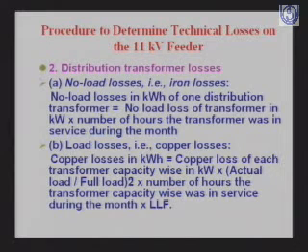So you can see that this ratio is in square. So if the transformer load is at 10%, 40%, 60%, 100%, the copper loss will not vary in linear proportion. It will vary in a different way. So that's why whenever any one of us is doing an audit on such a system and suggesting some recommendation, such as switching off a transformer or shifting load from one transformer to another, please be careful and look into this aspect.